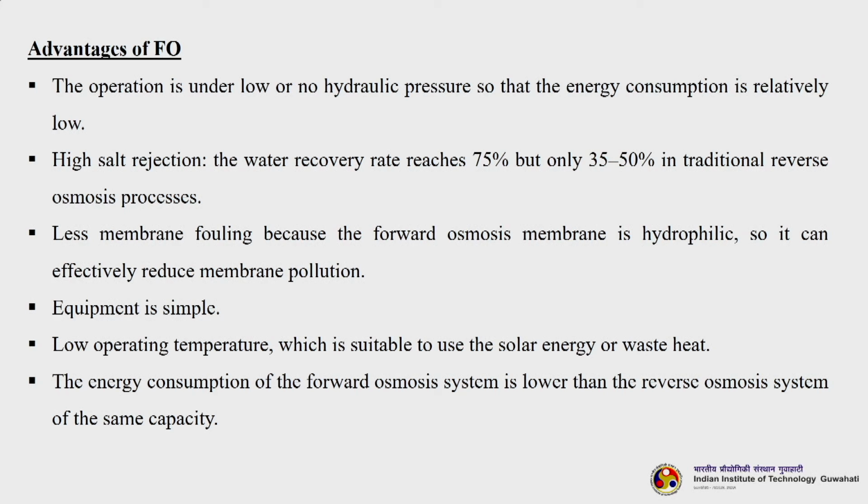High salt rejection: actually the water recovery rate reaches about 75%, but only 35 to 50% in traditional reverse osmosis processes. Less membrane fouling, because the forward osmosis membrane is hydrophilic, so it can effectively reduce membrane pollution. The equipment is relatively simpler. Low operating temperature also, which is suitable for using solar energy or waste heat. So, the energy consumption of the forward osmosis system is lower than the reverse osmosis system of the same capacity.